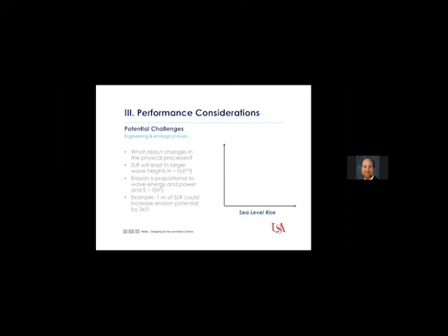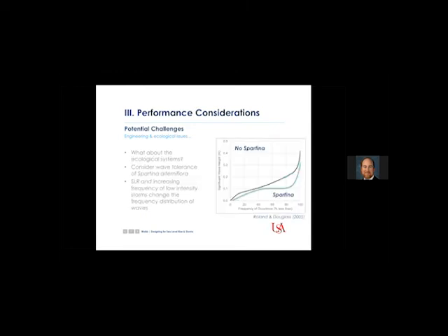Then what will happen is, with time, as sea level rise goes up, our wave heights will increase because of the larger water depth. Our erosion potential increases in a nonlinear fashion. As an example, 1 meter of future sea level rise could increase your erosion potential by a factor of 3 over the life of a project. And that's a fairly substantial increase.